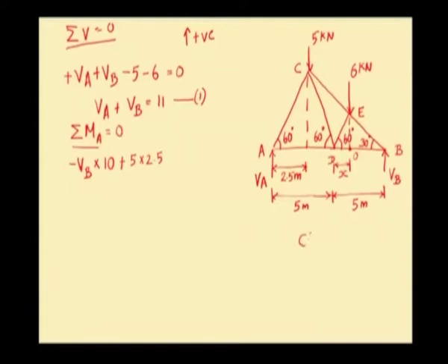So, in triangle DOE, cos of 60 degree angle will be adjacent side x divided by the hypotenuse will be DE. Now, the length of the member AC will be 5 meter, because triangle ACD is an equilateral triangle, AD is 5 meters. So, AC will also be 5 meter. Now, the distance DE will be 2.5 meters.